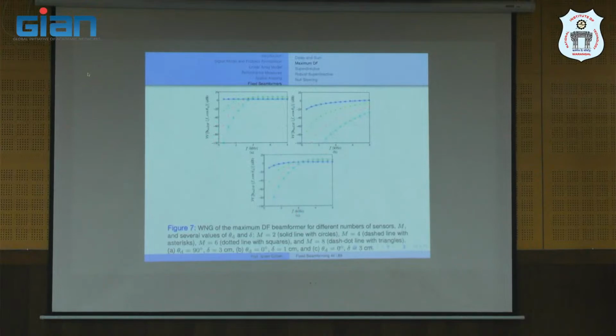It means that in a practical environment, we will get amplification of the thermal noise at the output of the beamformer, which means that the maximum directivity beamformer is not robust to thermal noise because it cannot handle such errors.